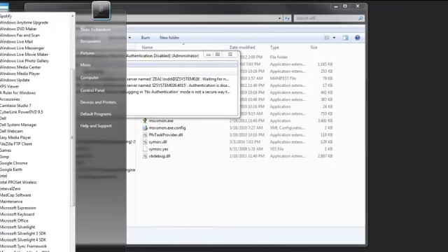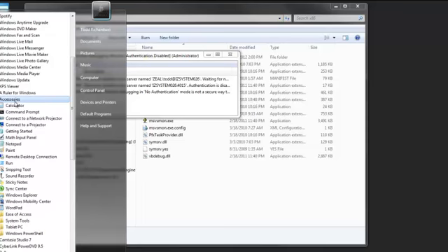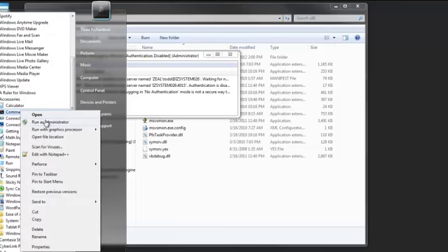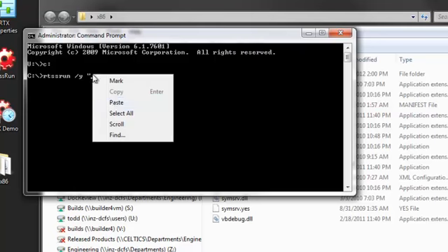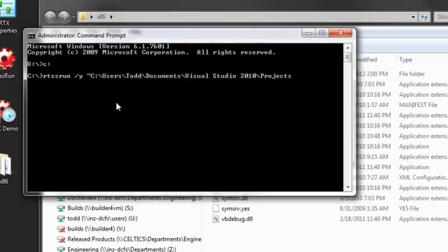The next setup step on the target system is to start the RTSS application we want to debug remotely. To do this, we'll open a command prompt and type the following: RTSS run, which will use the RTX RTSS run utility to run the application, followed by the /y flag, which is required so Visual Studio can attach to the application, followed by the path to the application, which for this example is test.rtss.